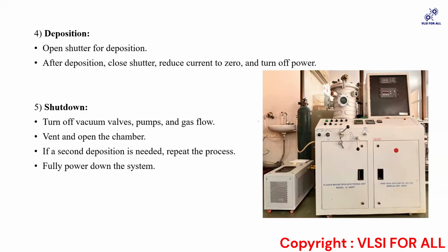Then chemical vapor deposition, that is CVD. There are multiple CVD techniques: LPCVD, low pressure CVD, plasma CVD, MOCVD, metal organic CVD, then ALD, high vacuum CVD, thermal CVD. Mostly we are going to use MOCVD, epitaxy growth, atomic layer CVD, and plasma enhanced CVD.